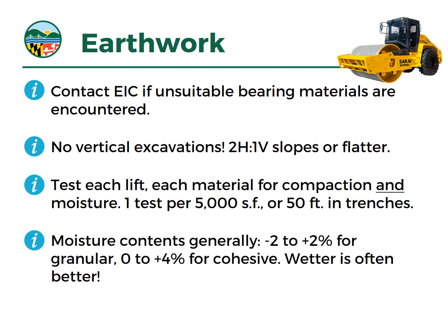We would say that testing of materials for earthwork is very important. Now, I would say that any kind of borrow material should have had a recent test at the borrow pit, less than maybe 1 or 2 months from the time of delivery. We want to make sure what you're getting on site, if it's coming from off-site sources, is what you expect. Or if you're borrowing on site, you want to have sufficient testing, that being Proctor compaction testing, Atterberg limits, and grain size analysis at the least, to understand what compaction characteristics you should expect.